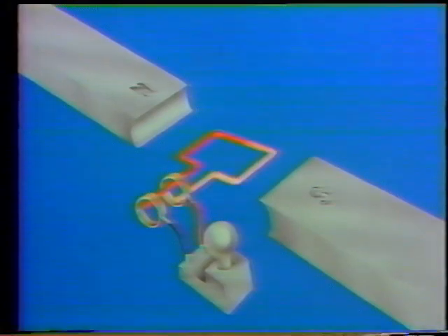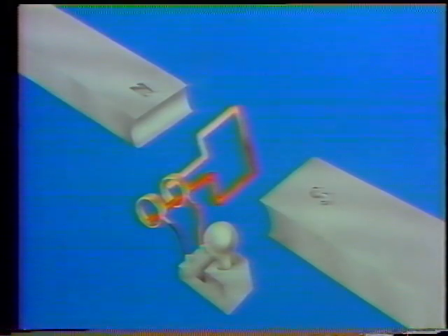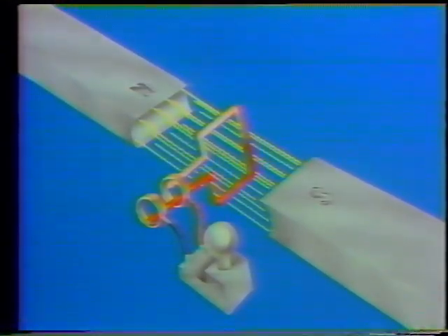In our generator, the magnet is stationary. It's not going to move. Since either the magnet or the conductor has to move, we have the conductor, the loop of wire, rotating between the poles of the magnet. Now, since we have a magnet, a conductor, and relative motion, we can induce voltage. As I move this conductor in one complete rotation, it's cutting through the magnetic field, right? You know that the magnetic field is made up of lines of flux that always move in this direction. But each part of our loop of wire cuts through these lines in two different directions.